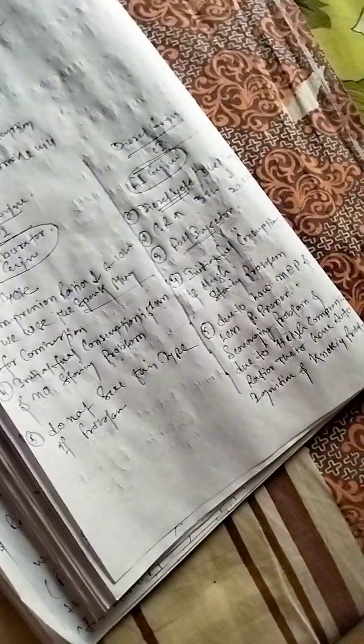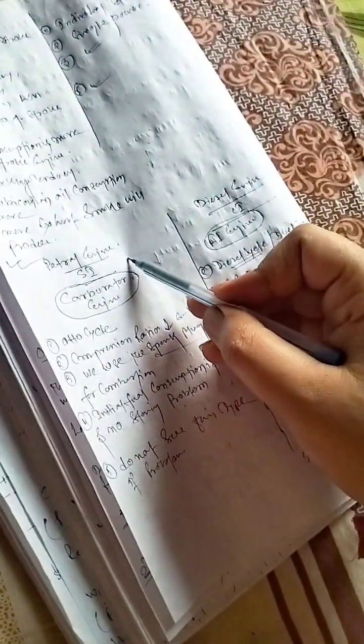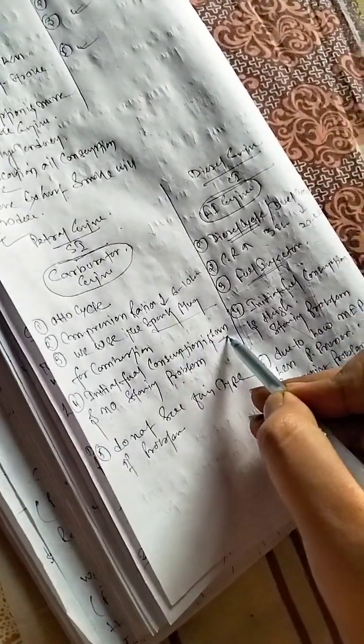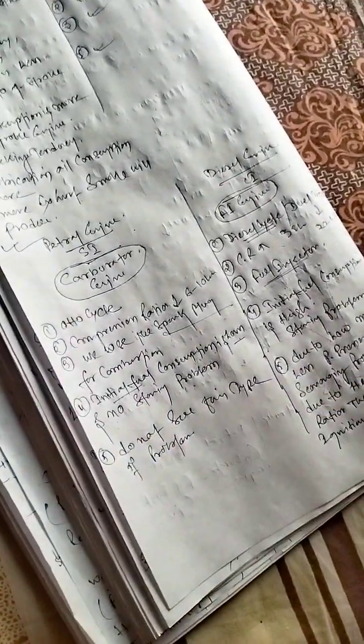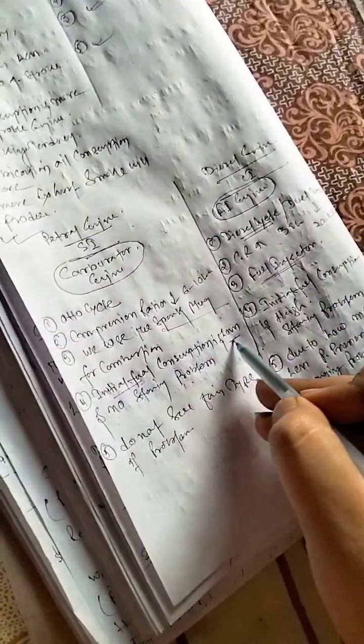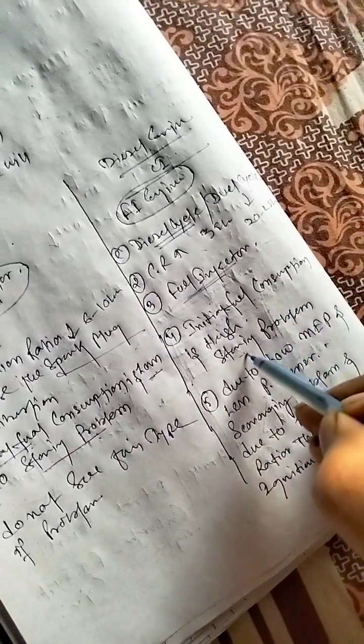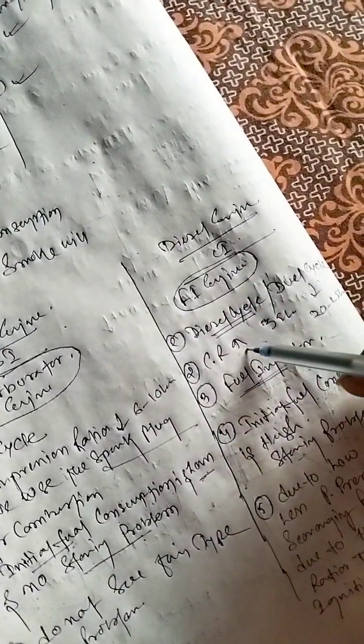Initial fuel consumption, when we start our vehicle, like a petrol engine, meaning the vehicle which runs on petrol, is less. Initial fuel consumption means when you just start your vehicle, at that time the fuel consumption is less and there will be no starting problem, so with one kick it will start. But in a diesel engine, initial fuel consumption is high and they have a starting problem. So why is it high, and why do they have a starting problem? You see here the compression ratio in the diesel engine is very high.